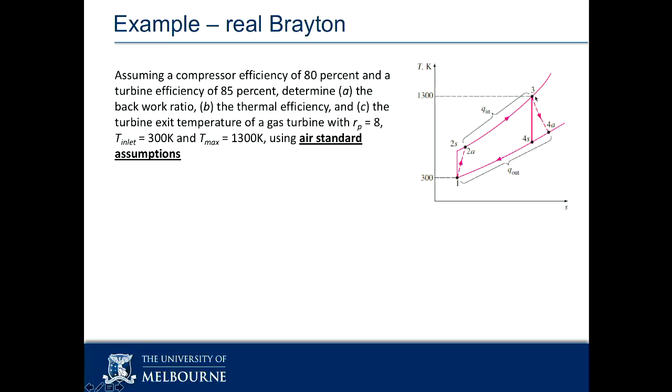On the turbine, which is trying to do work, is trying to release energy and release work, the amount of work I can get out is delta T times CP, 3 to 4S is the temperature, delta T. And if I have losses, my delta T is smaller, so I get less work out.